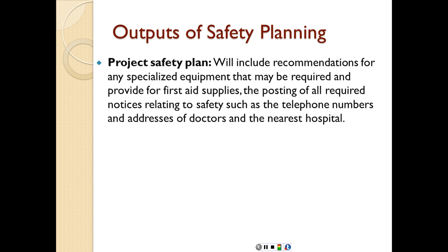The outputs are going to be, first, the project safety plan, which will include recommendations for any specialized equipment that may be required and provide for first aid supplies. The posting of all required notices relating to safety, such as the telephone numbers and addresses of doctors and the nearest hospital, information about reporting safety accidents or reporting hazardous practices on the construction site, reporting these to OSHA, as we're going to see some of the standard posters that have to be posted on site.